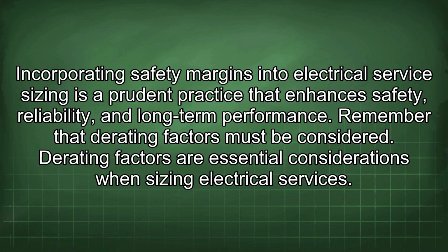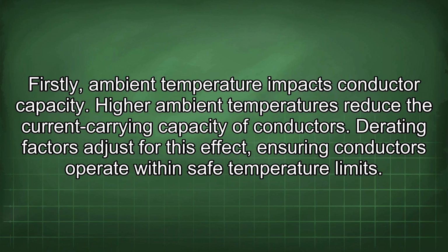Derating factors are essential considerations when sizing electrical services. Firstly, ambient temperature impacts conductor capacity. Higher ambient temperatures reduce the current carrying capacity of conductors. Derating factors adjust for this effect, ensuring conductors operate within safe temperature limits.